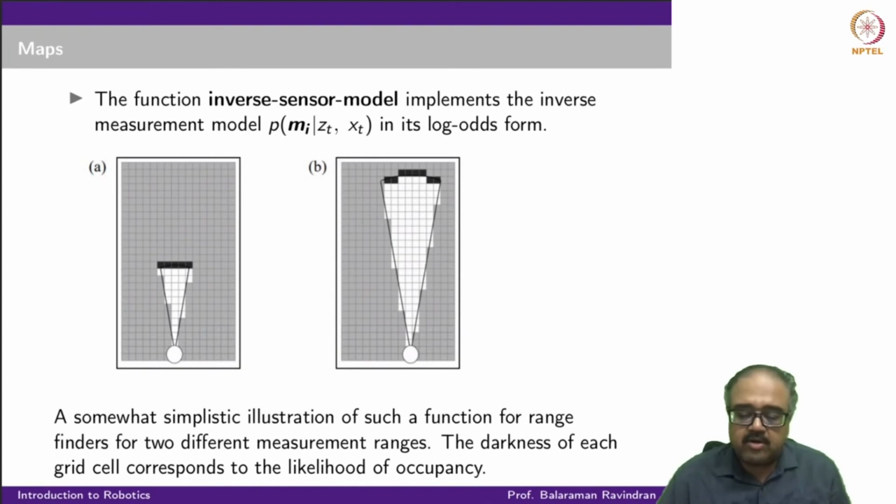The robot could potentially look at a lot more states here, and it can give you information about all of these, saying that they are clear, because this is in the field of view, and there is nothing that stops it until it hits the obstacle. Beyond the obstacle, the robot doesn't know what is there. Before the obstacle, the robot knows these cells are all free, and anything outside of this field of view or behind the obstacle, it can't give you any additional information.